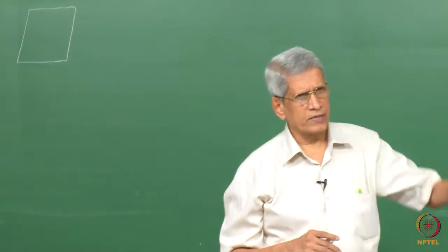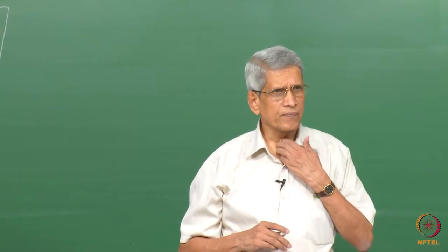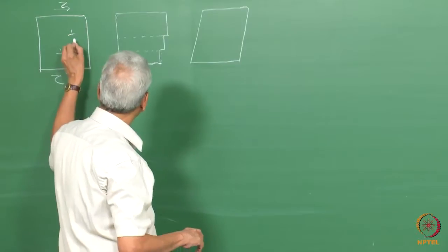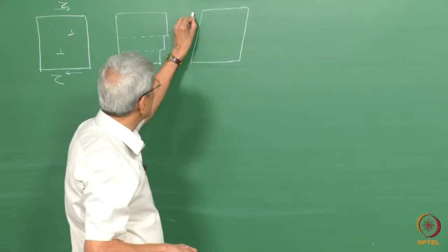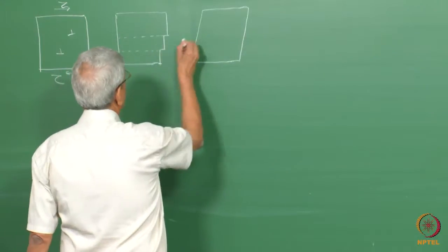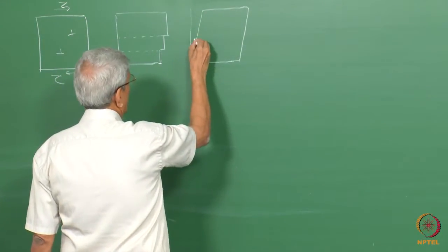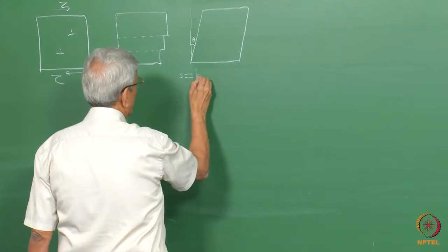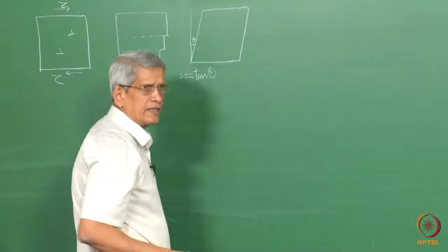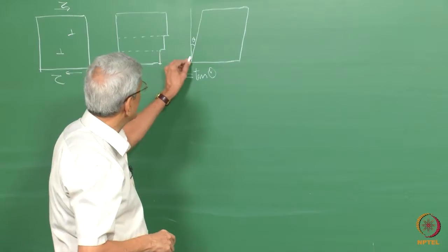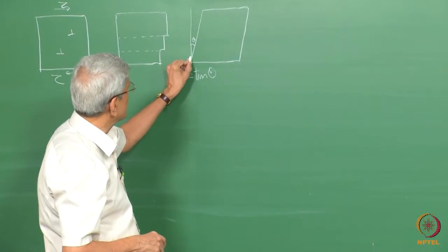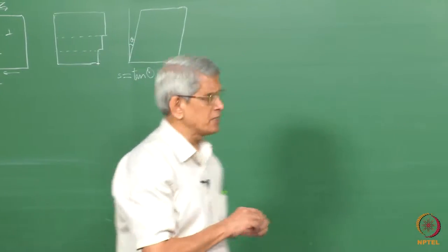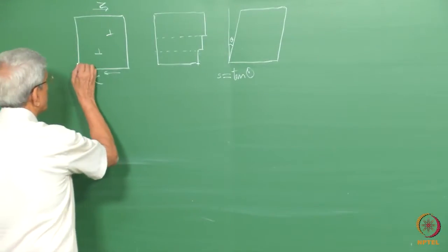Essentially, what has happened is that, and another thing which you consider is that when it has homogeneously sheared, because the deformation appears to be now homogeneous, whereas here it is heterogeneous, if we try to find out what that angle is, this angle, the shear S will be equal to tan theta. That is what we define as the shear. That means that at every point the shear is proportional to the height at which we are considering it. So, it is a homogeneous deformation.